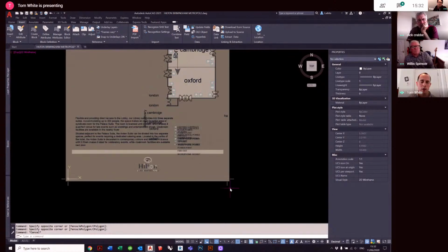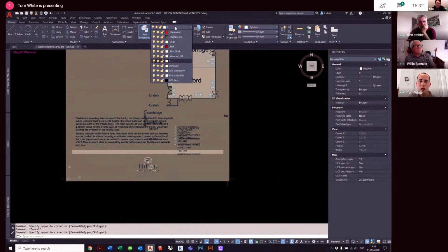I think, Tom, possibly one way of describing it is it's not a single image. This has components to it. It's come in and has components. And what you're about to show us is that, unlike a single image, which we wouldn't be able to manipulate, we can manipulate this. And this is why it's so powerful. It's unbundled its components from Illustrator, and this is where the pleasure comes, so to speak. Absolutely. So in this circumstance, I've got a really good feeling that it's not from a DWG program. It's probably from Illustrator. When you import a DWG, it will often have PDF as the start of the layer names, and then it will have the actual layer name.